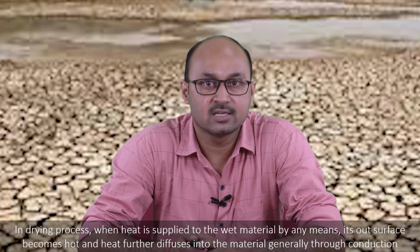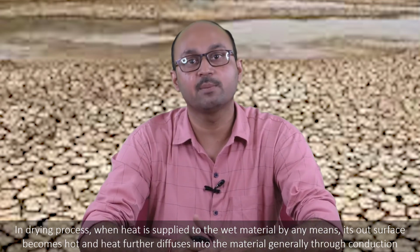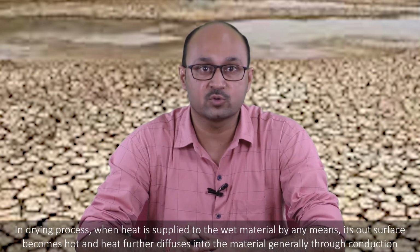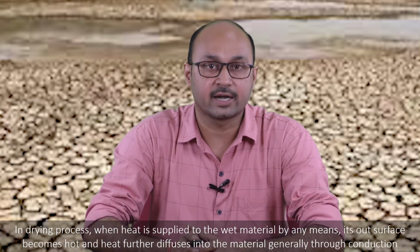Then we will try to understand what the mechanisms are taking place inside the food material under the drying process. In the drying process, when heat is supplied to the wet material by any means, its outer surface becomes hot and heat further diffuses into the material, generally through conduction. So basically two heat transfer mechanisms, convection and conduction, are continuously taking place inside the material. And again I am just reminding you, it is not a simple process. It is a complex process, and different types of heat and mass transfer mechanisms are continuously taking place inside the material during the whole drying process.